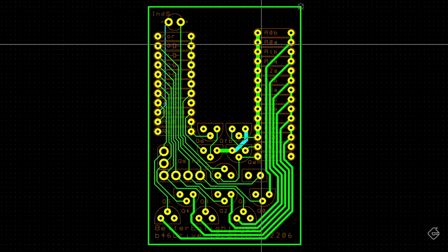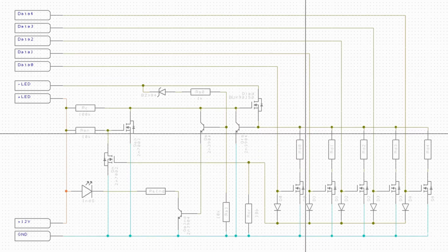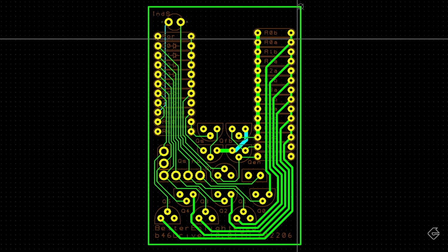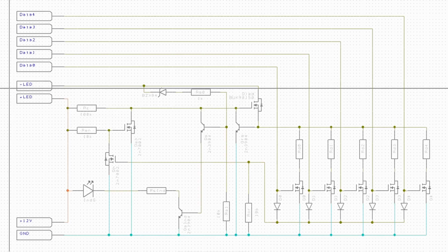I've actually laid out room so that each resistor in our schematic over here corresponds with two resistor footprints over here. And the reason I've done that is because the specific values of resistors that we're going to be using for these drivers are very precise. And it might be easier to create some of those high precision numbers using two resistor values in parallel. Now I'm going to add in the LED connectors over here.